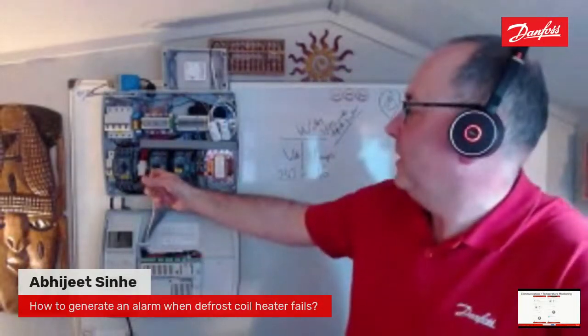There is a lot of discussion on things like that at the moment, on monitoring the current or the power usage of a refrigeration system. For example, you could have a CT on your defrost heater contactor, and if that is not pulling what you would expect amperage-wise, then you can say maybe one of my 3 defrost heaters is not working. So there are ways to do it. Nothing as an off-the-shelf solution as far as I know, but the easiest way would be to measure the amperage that you're pulling on your defrost via CTs, for example.